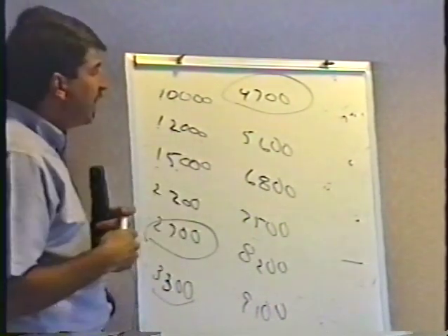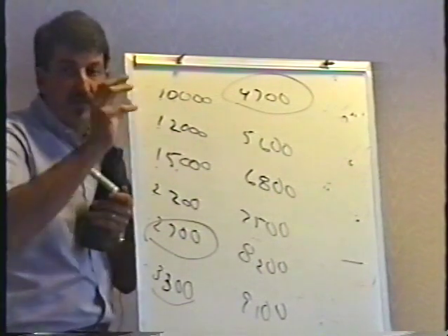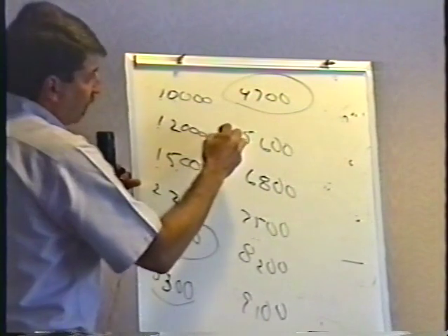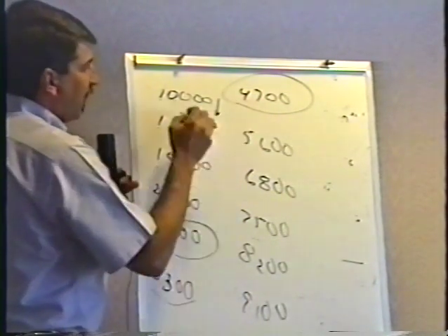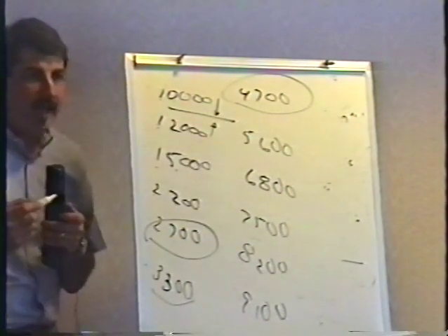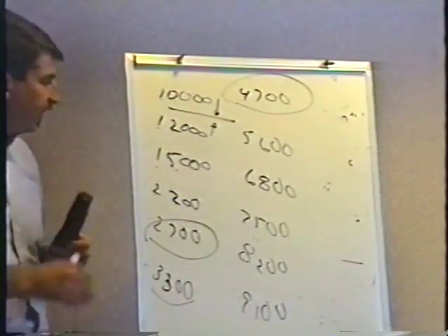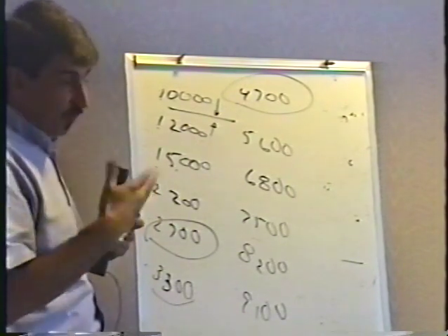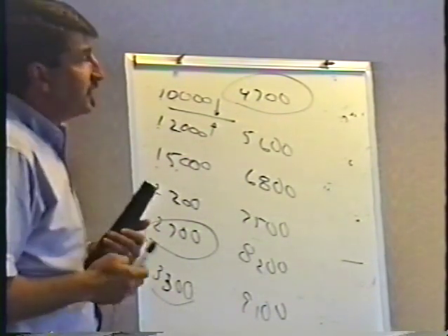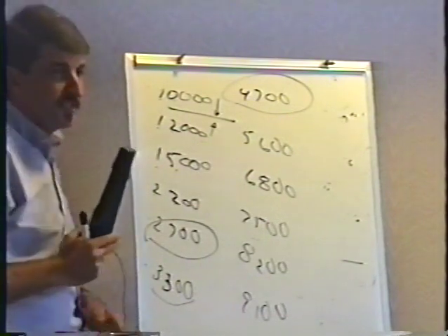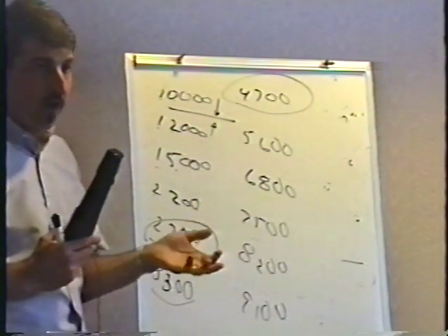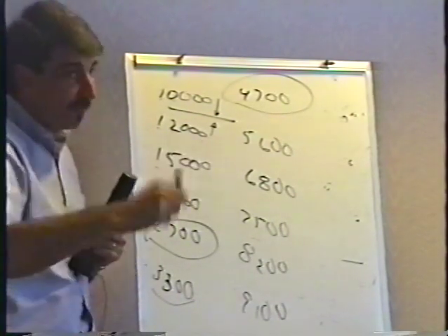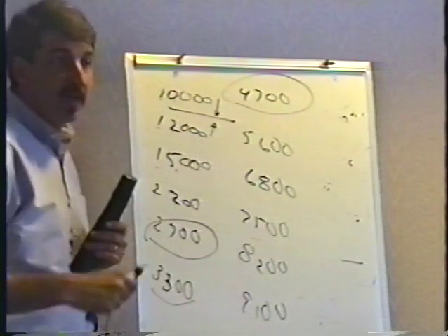You don't see the 2Ks. And the reason you don't is that, remember the tolerance, the plus and minus part of this whole deal. If you go up a little bit in tolerance this way and down a little bit in tolerance this way, right in the middle is kind of where they meet anyway. So you don't see every value under the sun. So it's pretty easy after a while. You look at a resistor. For instance, if somebody tells me that they've got a resistor that's 73 ohms or 730 ohms, I can say almost without a doubt, bullshit. You don't have that resistor because they don't make that resistor. How could you possibly have it?